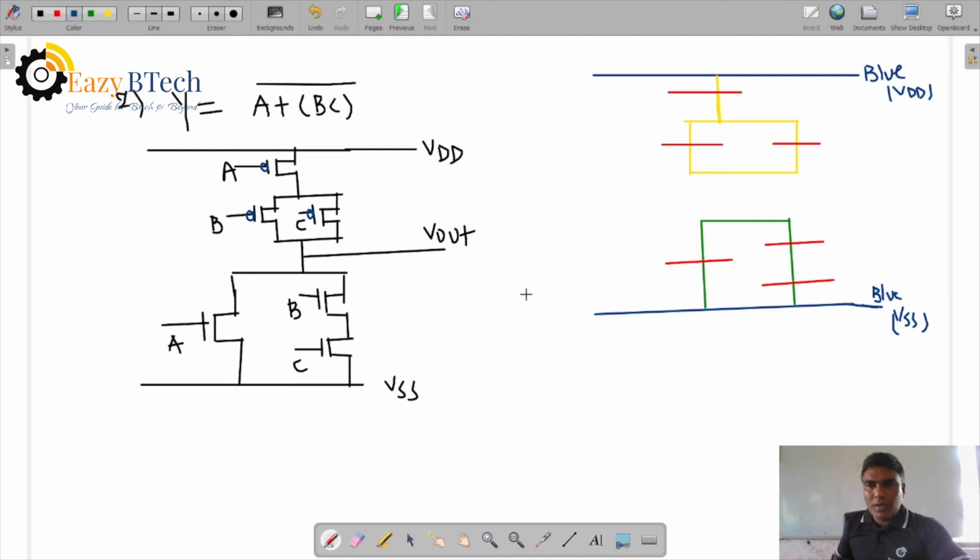And also we have the output terminal interconnection with this and we can take it as the output. So Vout is also blue color, right? Then represent polysilicon inputs A, B and C. Here also A, B and C, with B and C parallel. Now the interconnection point is there.